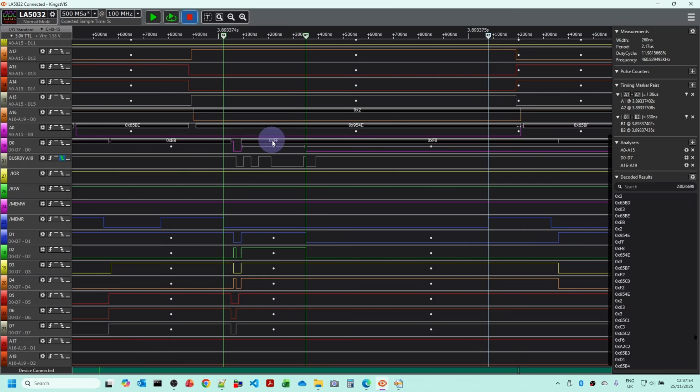So the 0xFF then does become F8 for the rest of that period of time. You can see that if we weren't extending this, if this was only taking perhaps 240, 300 nanoseconds, which is what the default timing would be without any extended wait states, then we would potentially miss the data here.